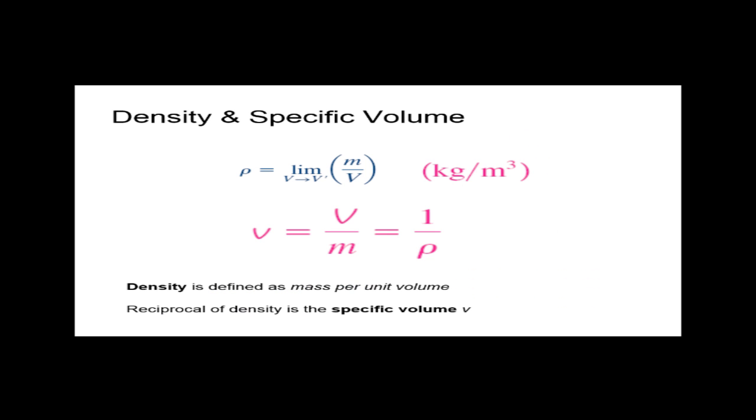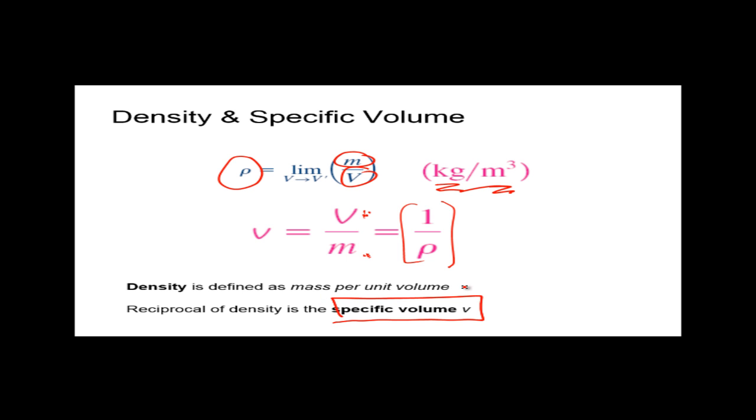Density, specific volume. A lot of people have seen mass density before. It's just how many kilograms per cubic meter, true? So it's mass divided by volume. What happens if I reciprocate that? 1 over mass density, that's volume per unit mass. Well, would that ever be useful? Well, we use it a lot in thermodynamics. It's called the specific volume. I know that it seems trivial, but if you have one property and you want a new property, just take the old property, reciprocate it, give it a new name. That's what we did. Okay? So specific volume is a new property.